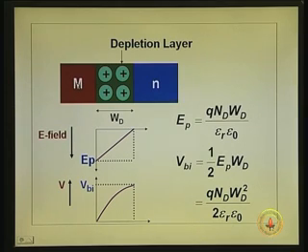if it is P, you have got the metal there, all the depletion layer is on this side. If it is P plus, there is no depletion layer. If it is metal, there is no depletion layer here. The electric field actually is plus here, minus there, from right to left. Okay. Now, by solving Poisson's equation, you know that the electric field will be linear, peak at the junction, and linearly decaying, it is 0 at the other end of the depletion layer. Okay. What is the peak value of the electric field?